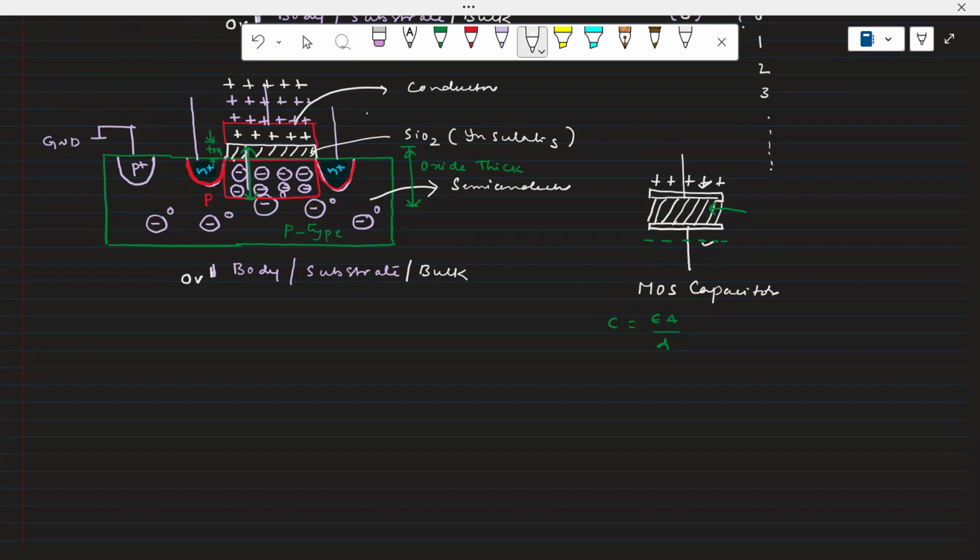Instead, the negative charge will be developed from the free carriers available in the n plus region, and that will occupy the area below the silicon dioxide. That is also electrically negative charge, electrons. Are you getting the point? Therefore, how much positive charge you put on the top plate, the equal and opposite charge will be available below the silicon dioxide. Therefore, the electric field will be balanced there. So these carriers will be available more and more while we apply more positive charge on the top.